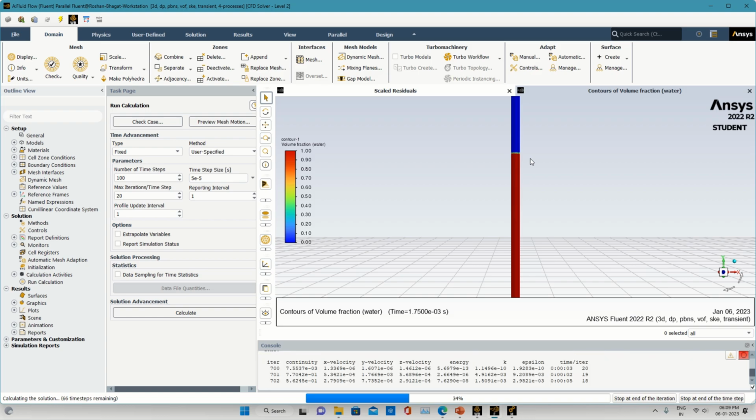So we have taken it 100. I will just try to show you with the help of 999 as a time step whether the same problem occurs or not. So this method is particularly suitable. Preferably, what you should do is take the smaller time step if possible. If we are not getting any kind of floating point exception error, you should always try first for a smaller time step, and then you should follow the method which we have specified right now, because unnecessarily you might be losing some time in performing the iteration which we had done earlier. So this is an alternative method which can be used to avoid the problem of floating point exception error.